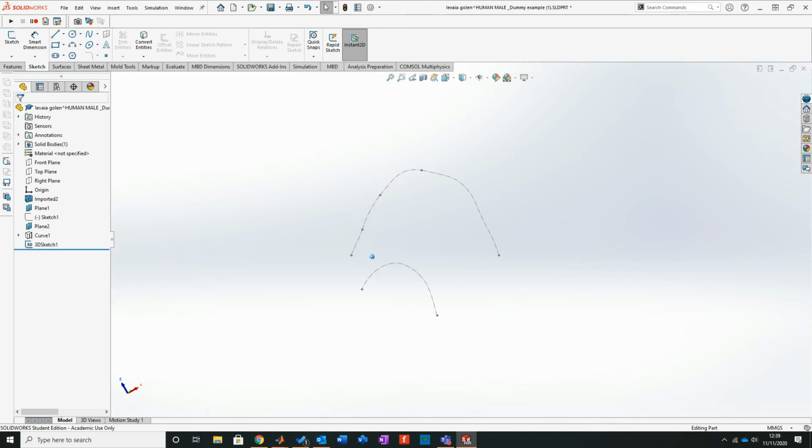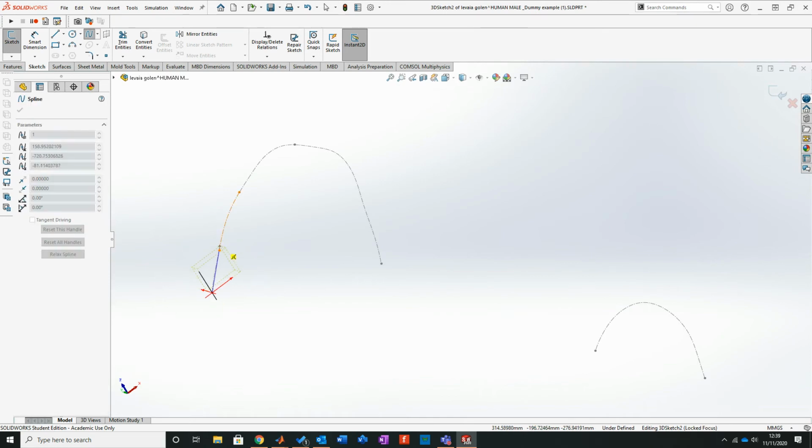And then confirm. And I'm actually going to turn off my curves completely. And now what I've got is something I can see, something I can operate with, and I just feel a bit happier, if I'm honest. So then I go back again. I'm going to go 3D sketch and bring in my spline, and then just look at tracing this. This profile now will become continuous. And what it will do in inconsistencies that I don't like, it should start to try and bend the profile so it becomes a bit more smooth.